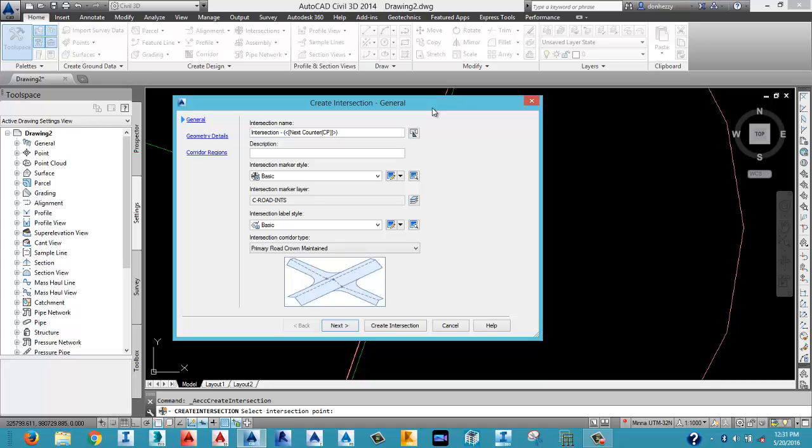Go in again, make sure your intersection snap is on, and then you select the point of intersection. Intersection snap is always an X icon which comes up whenever you want to select. Like now, if I zoom in on my design, you can see the X.